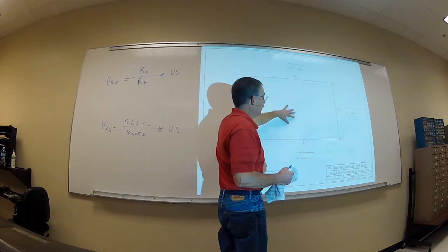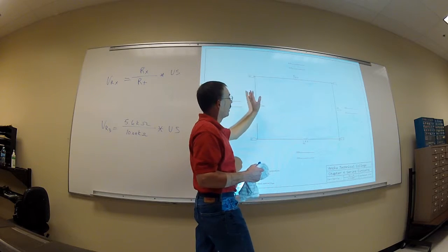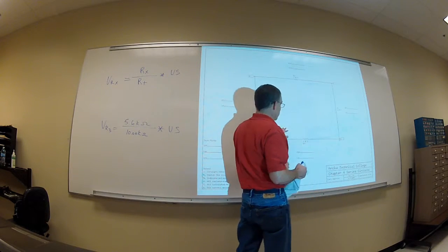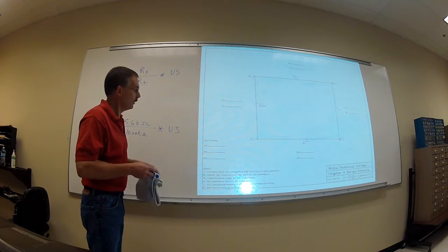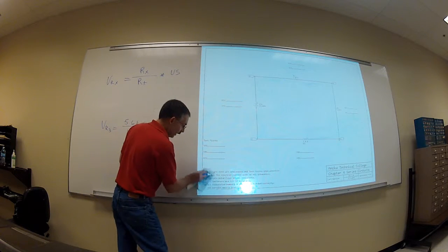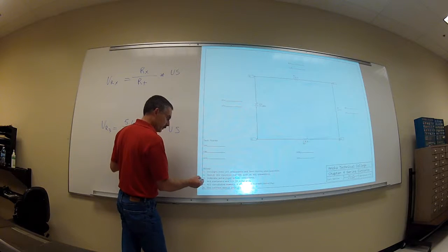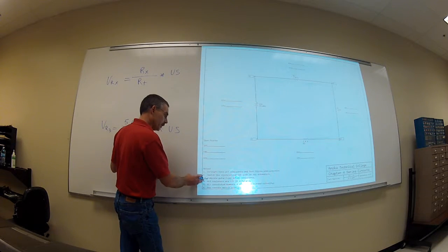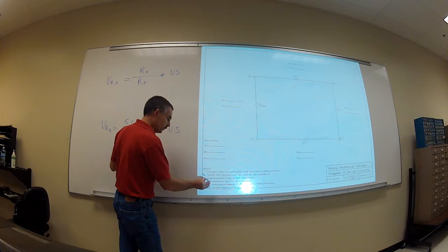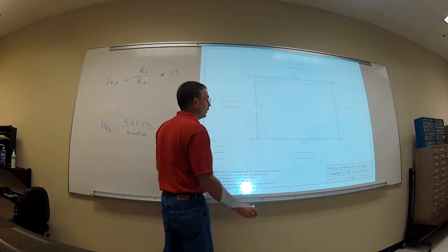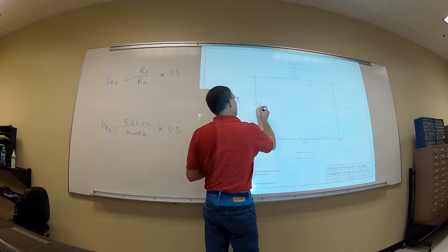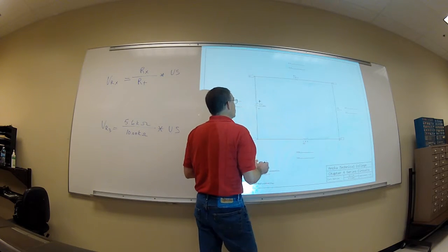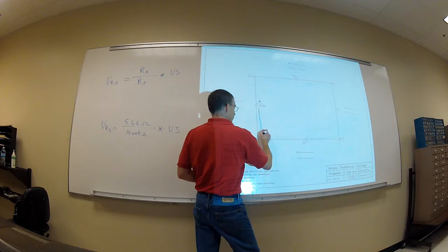So our first step then is that we need to find out what all our voltage drops, our IR drops, are. Okay? That's our first thing that we need to know. Again, we always want to draw in the electron current path and the polarities, which are very important. So we want to do that first. Okay, so is my current going clockwise or counterclockwise? Counterclockwise.